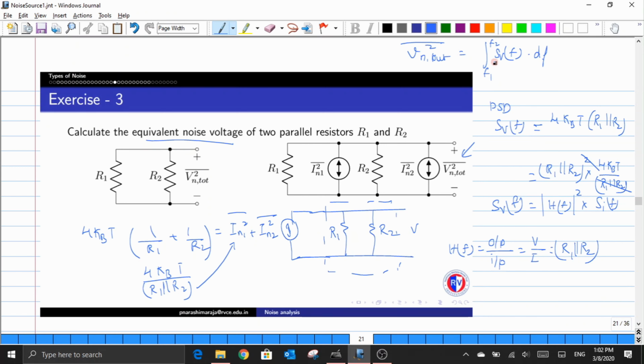So again, when we look carefully, the power spectral density doesn't have any frequency term inside it, which is completely a constant, due to which one could take this power spectral density term out of the integral, and when we perform the integral with respect to df, we would end up having a delta f, and since the frequency band is not given, one can consider the band to be equal to 1 Hertz, and due to which the expression of this power spectral density in short gives us the variance of this particular network.